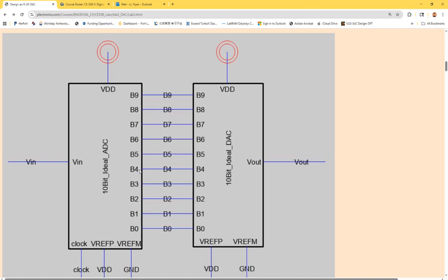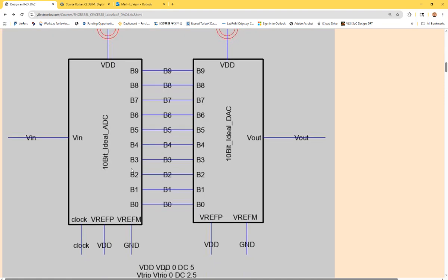Why is it called VDD? VSS sometimes, VCC sometimes, based on the transistor's terminals. VDD is usually for the CMOS technologies. The top pin is the drain terminal, and drain starts with D. That's why it's called VDD as a convention. For VCC, the older technologies used bipolar transistors with the collector on the top. That's why it's called VCC.